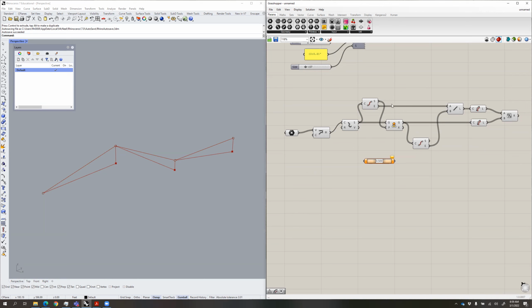I have to go backwards in time to this component right here, the explode component. This is where the curve got divided into segments. So we're going to take that S component right there and bring it into this. Now this little tool allows you to extract some kind of point along the length of that line. It's extracting a length based off of what's known as a parameter, basically a number between 0 and 1 that represents the overall extents of that line. So let's just put it somewhere near the middle, like so. This is going to be the location of the label.